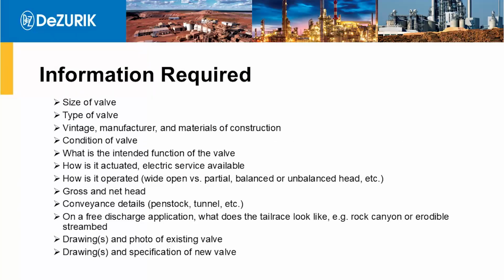Those are the 3 types of valves, and this slide is to give you a little bit of information on what you should think about when you visit a customer asking about a valve. So what's the size, what type of valve is it, if it's existing, what's the vintage, what manufacturer. Those are all things that we need to know. How is it operated is important. Are they going to operate it wide open or partially open? Is the head balanced or unbalanced? It's very important to know.